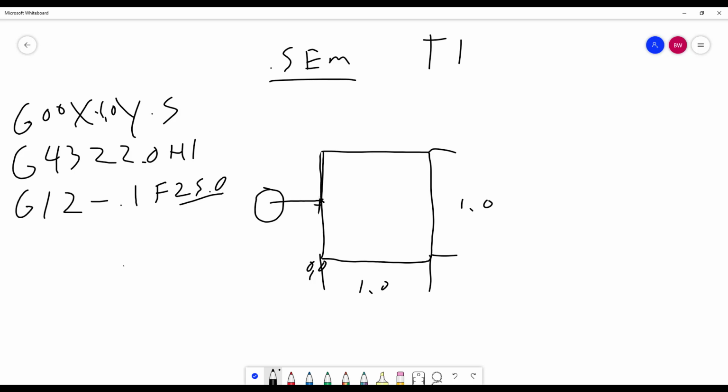Also, if you change cutter sizes randomly, then you've got to reprogram. That's the other issue with compensating numerically in the program, by changing the actual coding, because then you have to reprogram. Now, if you're using Mastercam, you can repost very easily. So if you are taking the Mastercam course, you'll see there are different ways to compensate. This would be the control method in Mastercam. It's also on my YouTube channel, so you can check that out.